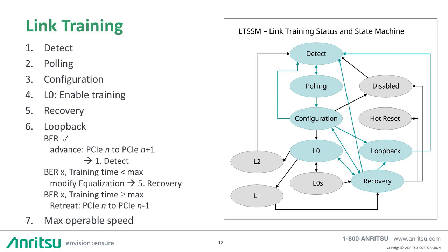In Phase 5, recovery, the SerDes, now in loopback mode, transmits feed-forward equalization tap requests, and the BERT pattern generator receives and interprets those messages and modifies its FFE scheme accordingly.